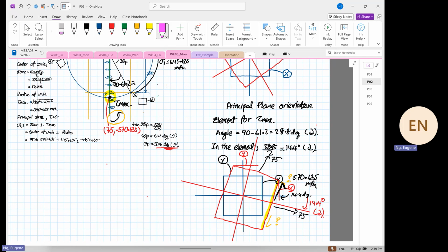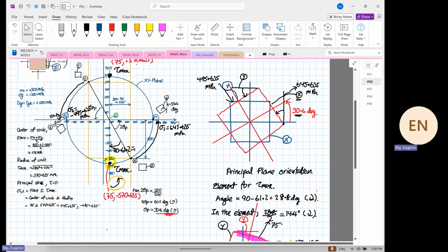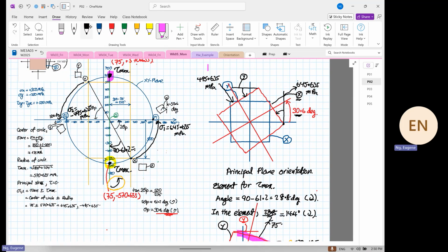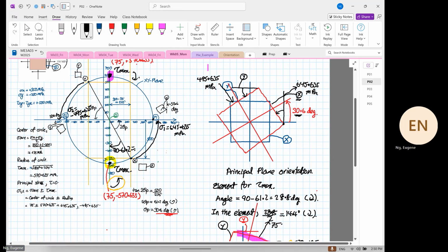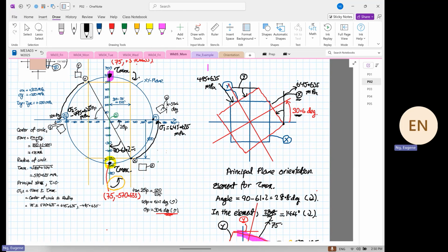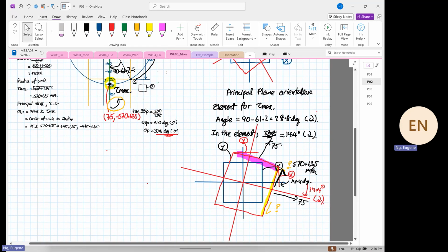Okay, let's look at the pink one now. Pink surface. At the pink surface, it corresponds to this dot over here. Okay, and we know the element on the top is going to rotate in what direction? Clockwise direction in terms of shear. Yes or no? In terms of shear, the element at the top has to rotate what? Clockwise. To go clockwise, you only have one orientation to go, and it is this orientation that you have to go.